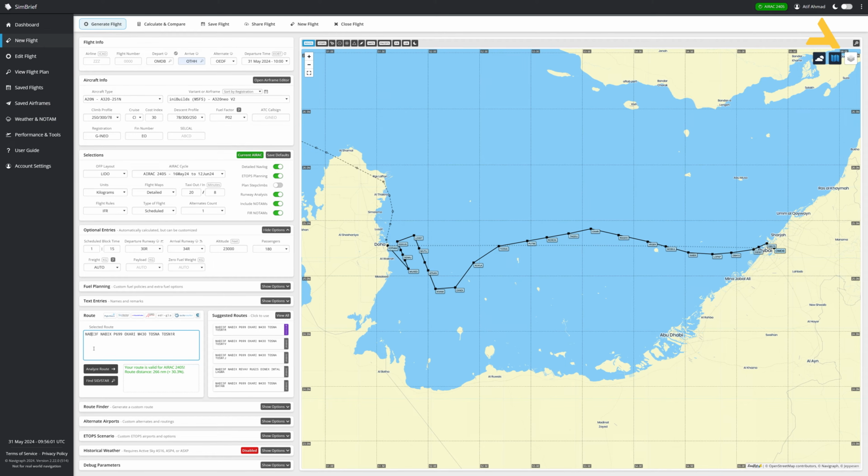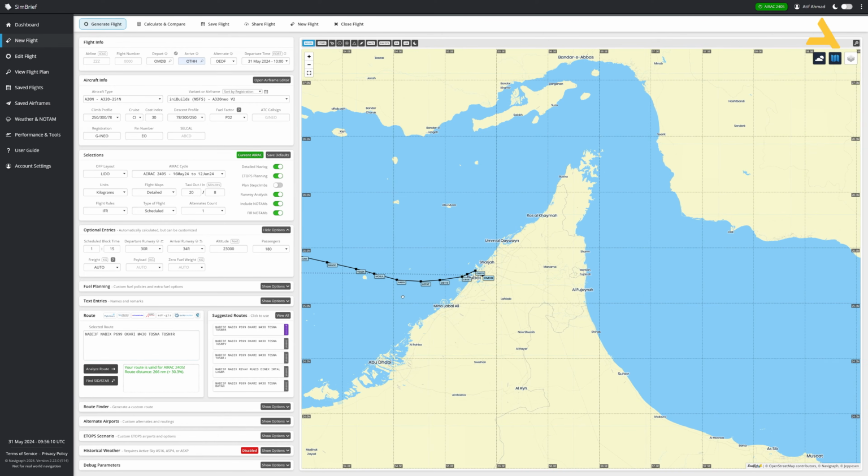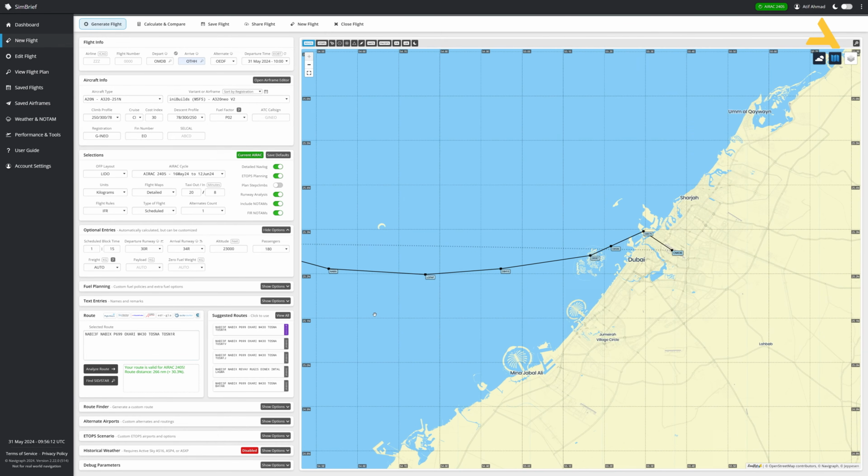Now if you look at this flight plan, this SID is actually taking you to the first waypoint, which is NABIX. So let's find this waypoint over here. Now this is NABIX. Now once you are flying out of OMDV, you're going to DB 570, 586, 587, DB 410, LOPAP, and then you go to this point. Now over here, you will not see all these points because this is a departure procedure which is specified by this standard instrument departure.